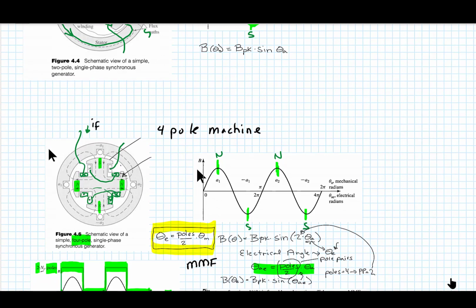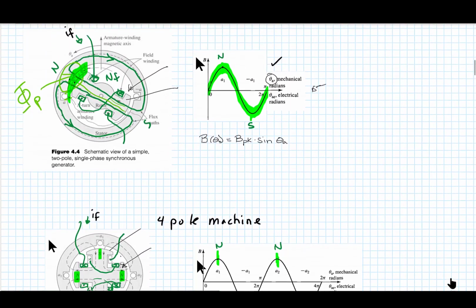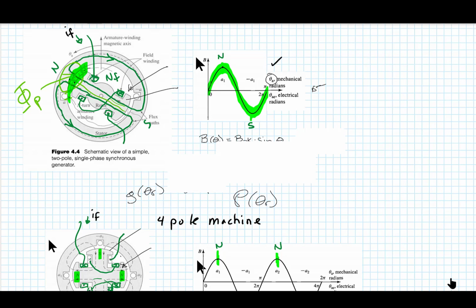And in this case, for these two types of rotors, the air gap as a function of theta r is variant. If you recall, going back to when we were talking about energy conversion, we introduced a permeance function that would be varying as a function of theta r.